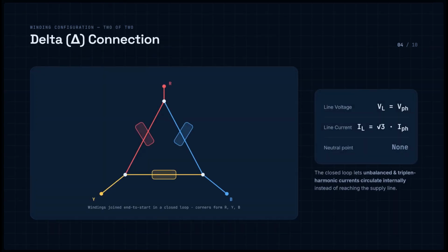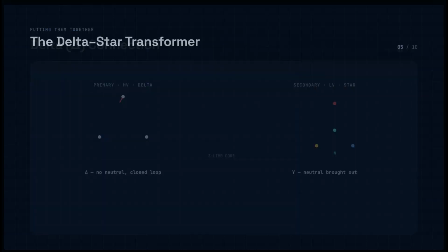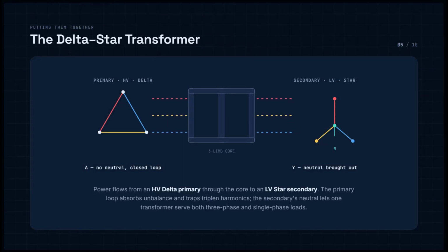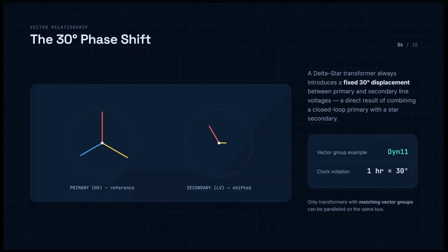Engineers continue to use these configurations because their electrical characteristics provide practical solutions to different system requirements. Advanced transformer arrangements, harmonic mitigation equipment, grounding transformers, zigzag transformers, active filters, and sophisticated protection systems can be used to address situations where the advantages of star and delta must be combined or where their limitations need to be managed. Ultimately, star and delta connections should be considered complementary engineering configurations rather than competing technologies.